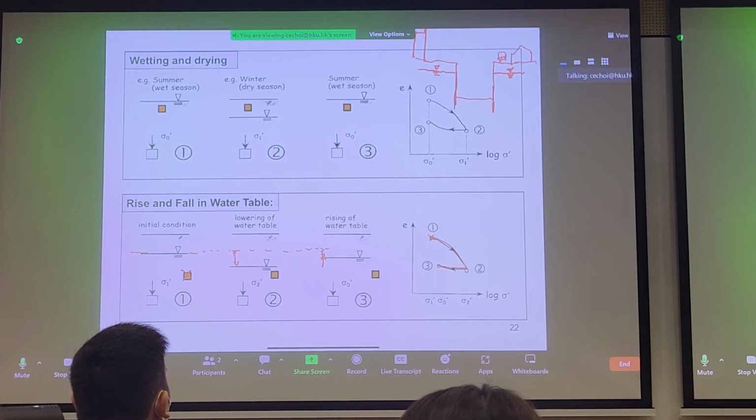What we're worried about when we draw the groundwater table down, let's say the groundwater table is also high in your excavation. So what we want to do typically is draw this groundwater table down to here so we can get machines inside to do construction.